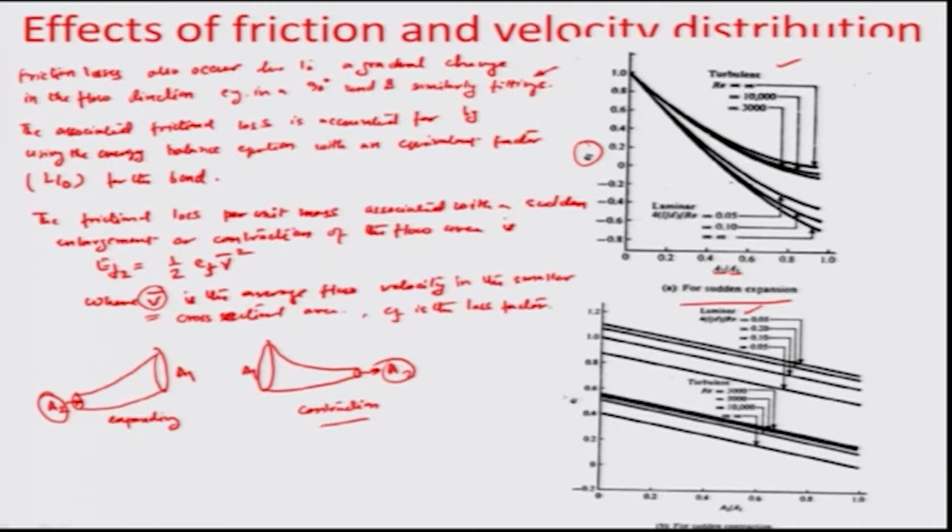And the way that you look at EF is really plotted right here, and these are two very important trends borrowed from elementary fluid mechanics, where we talk about the energy loss because of bending or contraction as a function of the area ratio.